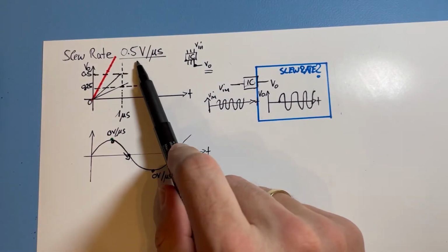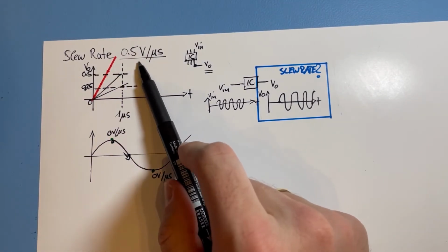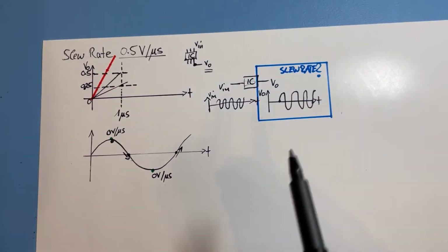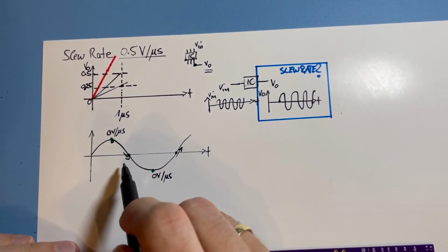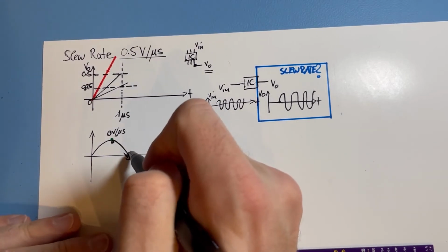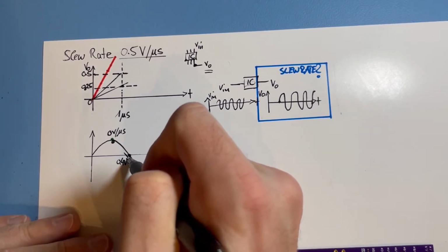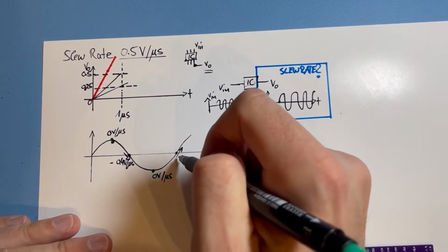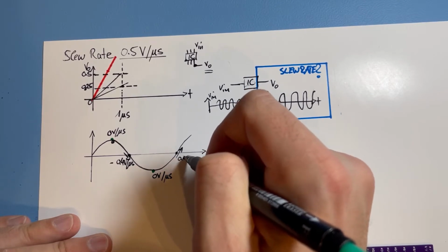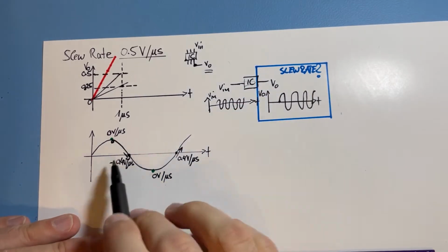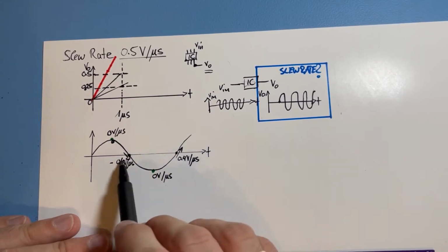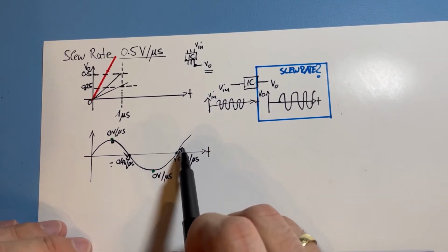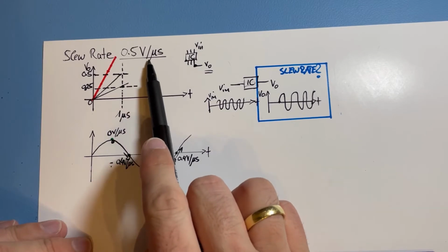And then I started to realize, oh okay, that number tells me what kind of sine wave I can support here. Because if you imagine another sine wave, let's say, just for fun, at this point 0.4 volts per microsecond, and here minus 0.5 volts per microsecond, and here it would be 0.4 volts per microsecond. So going down and up at the same rate, just with different sign, here a minus, here a plus. And 0.4 volts per microsecond, if it would be that way, we can support that. We have 0.5 volts per microsecond.